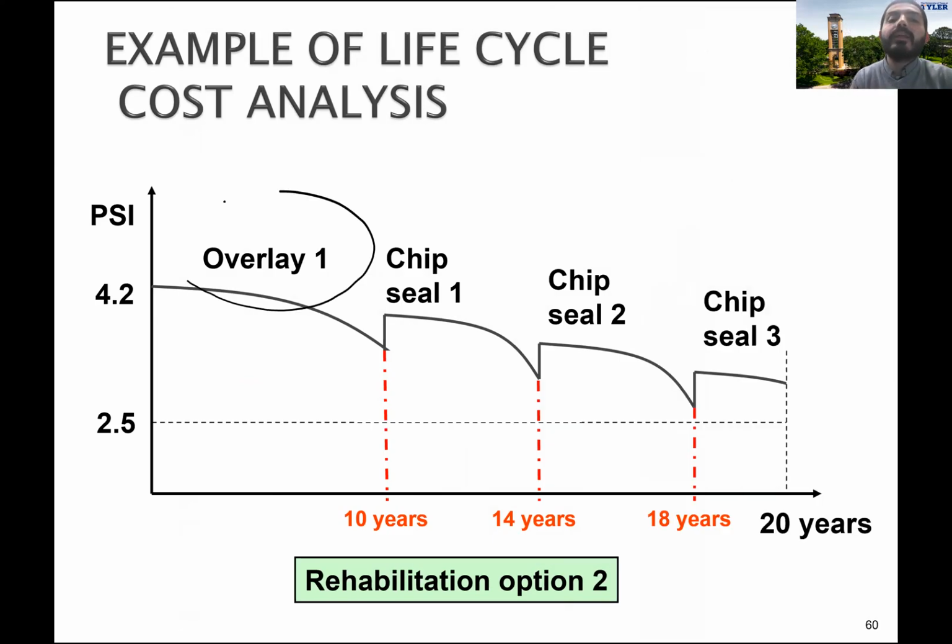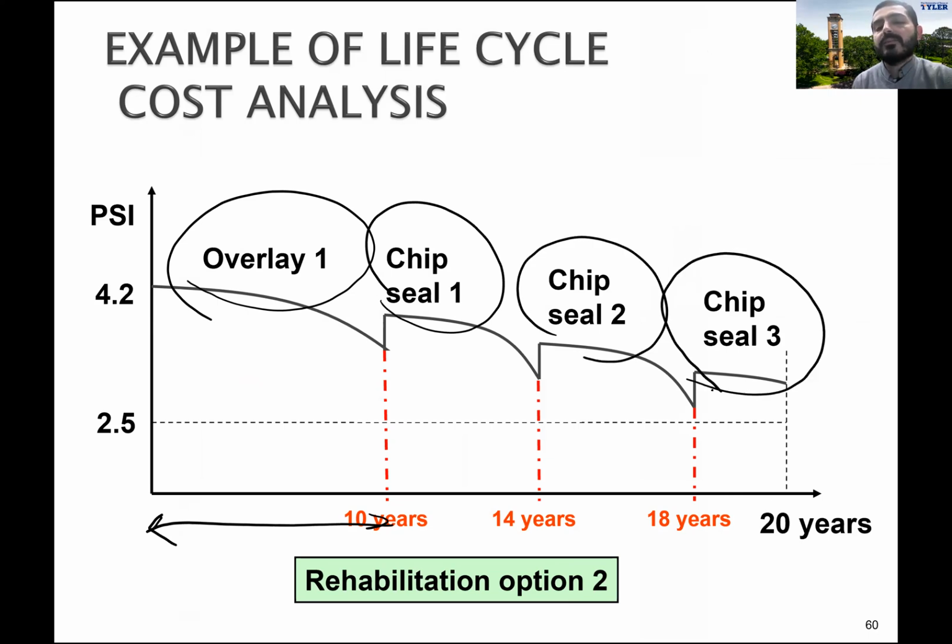I'm going to have an overlay. The first overlay is going to last for 10 years, but then I'm not going to do an overlay again. I'm actually going to do three different chip seals. The first one is going to last for 4 years, the second one for another 4 years, and then the third one for two years.